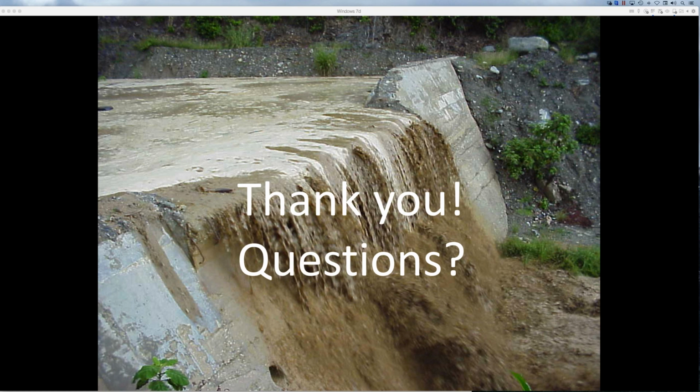So when you finish that water-only simulation, you get files that represent the snapshot of the steady state hydraulics. And then you start a sediment transport with a hot start option, and that will use your stored steady state simulation as the initial conditions for the sediment transport. So yeah, you can do that.